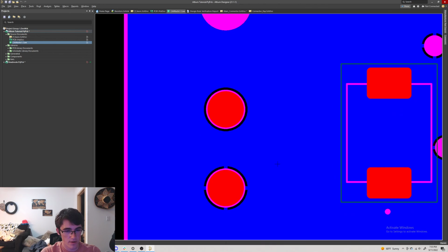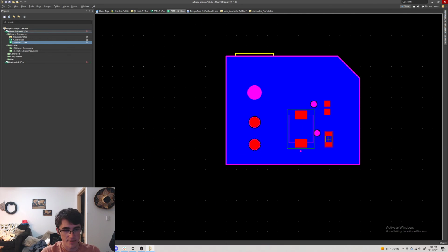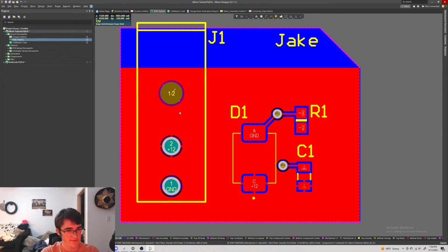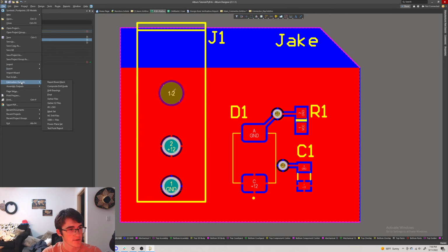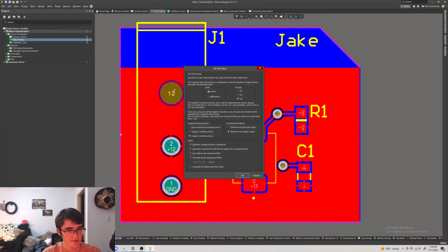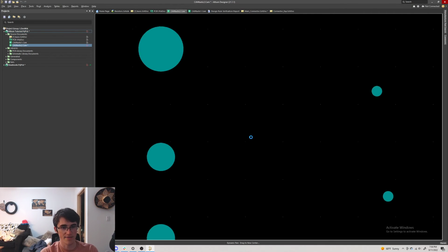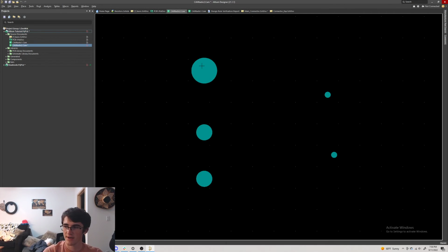But then you'll notice on this file there is not everything we need on it. Sometimes you also have to make a drill file to make sure that the parts of the PCB actually get drilled out. What you can do is go to Fabrication Outputs and then do NC Drill Files. Normally I don't touch anything here. I just hit OK. And then this is a whole separate file just to show where it needs to drill through the board to make those vias or those holes. You can see here, this is the 2 for the connector. These are the 2 ground vias that we made. So you can also save that if you want to include it in your project.